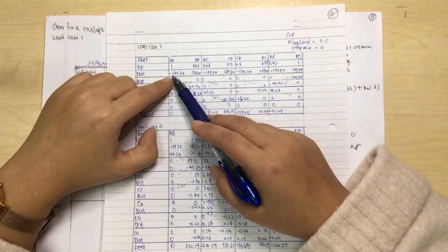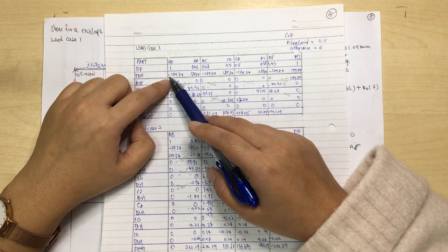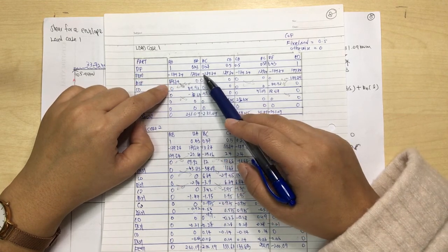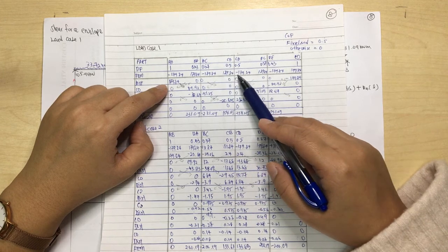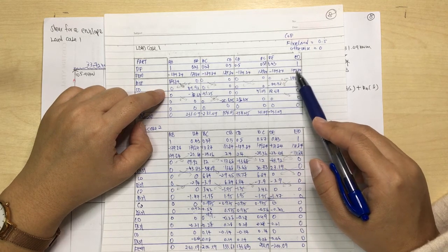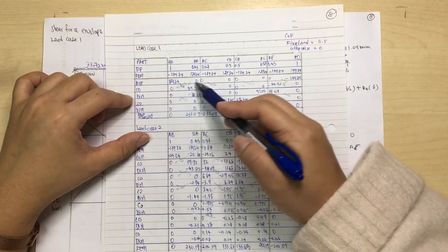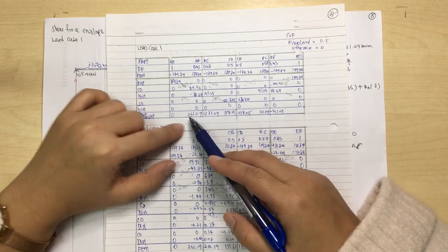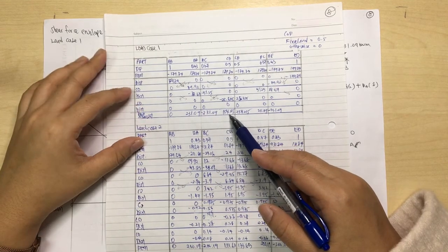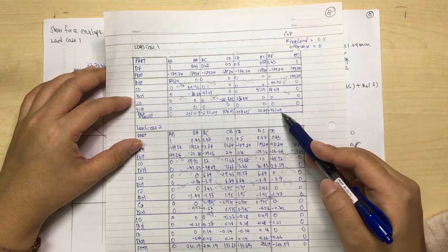You calculate the FEM, which is the value you calculated just now: negative 179.84, 179.84, and so on alternating. Then solve this using the moment distribution method, and you will get the moments: 0, 231.09, negative 231.09, 154.215, 154.215, 231.09, negative 231.09, and 0.